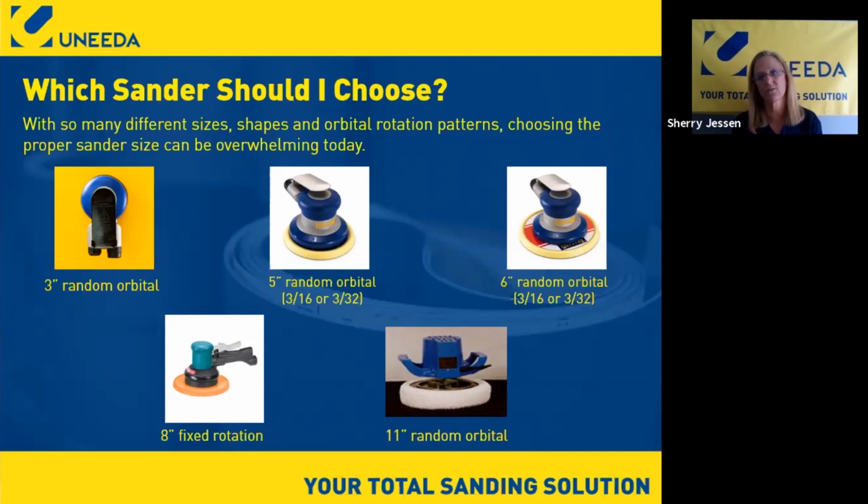3/16, 3/32. What's the difference? Well, you've got two different random patterns in the swing on the backup pad. The 3/16 swings a little bit wider, and it gives you a little bit wider swath. It also gives you a different swirl pattern. If you start to see swirl marks, you're going to see a longer, elongated swirl mark. And on the 5-inch, the 3/16 tends to be just a little bit more aggressive than the 3/32.